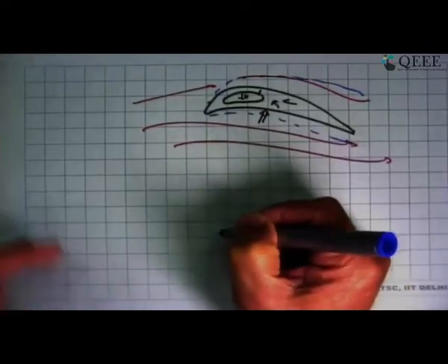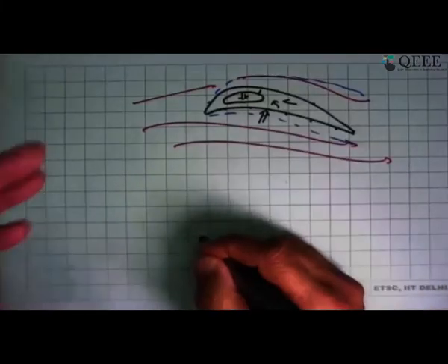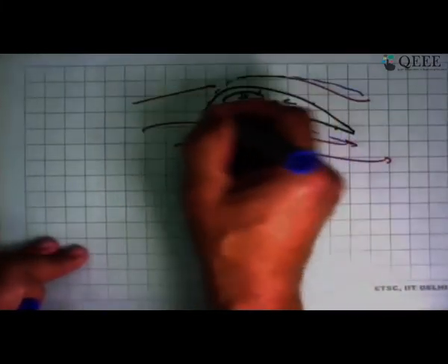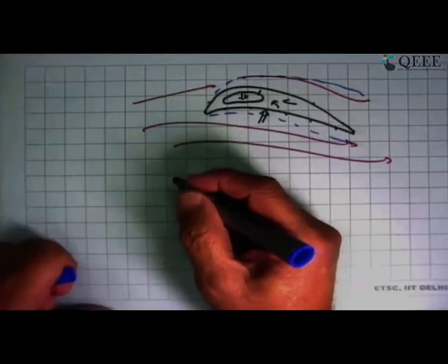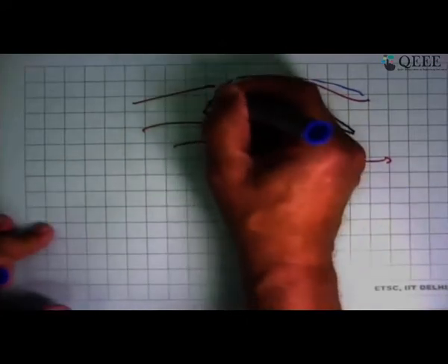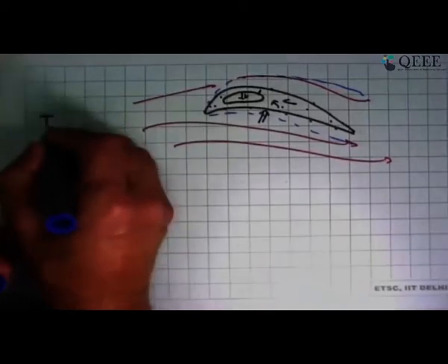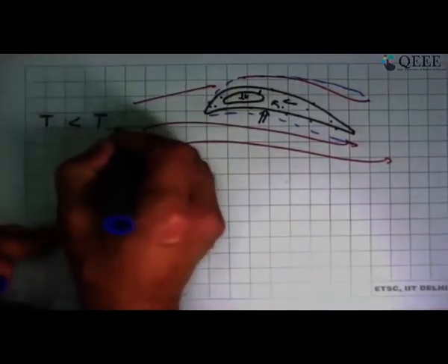And this is a hydrodynamic boundary layer. We know from fluid mechanics that the local skin friction coefficient at these places will be different. What it tells us is that the local heat transfer coefficients here will be very drastically different, which means that the surface will not be at a uniform temperature. There will be some temperature here, some other temperature here, somewhere it will be very cool, somewhere it will be very hot. And now the designer wants not only to cool it, but the objective is that the temperature at each point, the local temperature, should be less than a certain value.